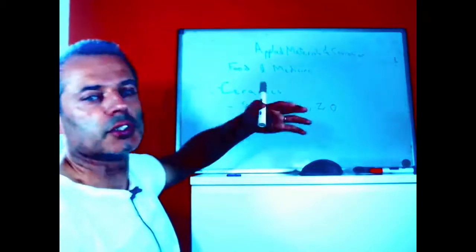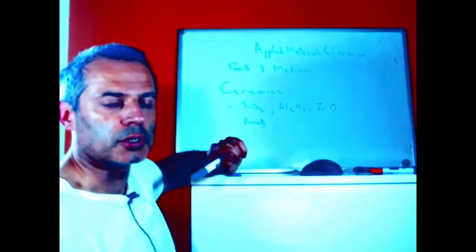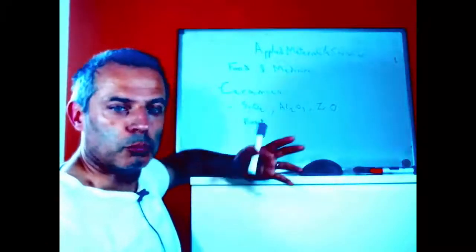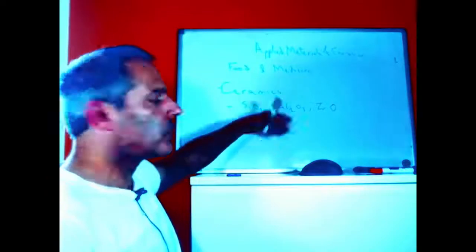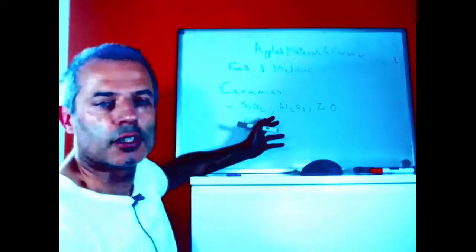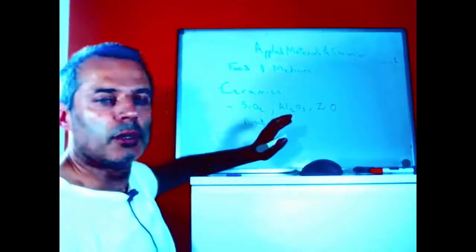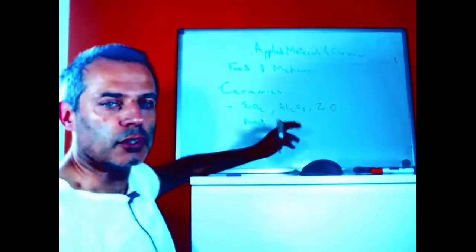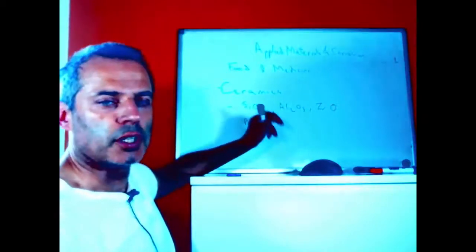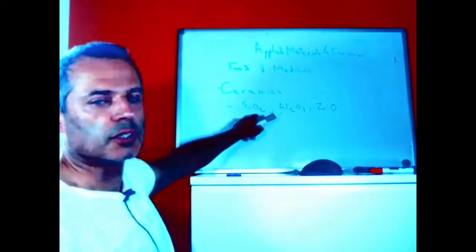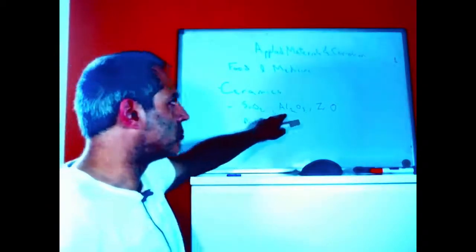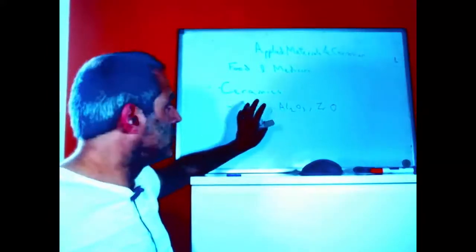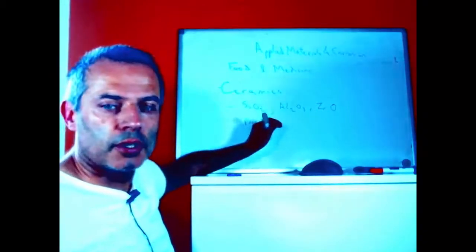If we have glass particles, they're usually relatively harmless. As long as they're either very small, then they'll dissolve, or they're big, then they just fall out to the bottom. So those are better than if we take a hardened steel type. Then we are releasing particles that contain heavy metals into the food or the body, and that's often a concern. It's usually not very much, and they're usually not very soluble, but it is a concern, and ceramics are better for that, because we can choose one where the products are not very harmful. And we still get very high stability, and we get very high hardness.